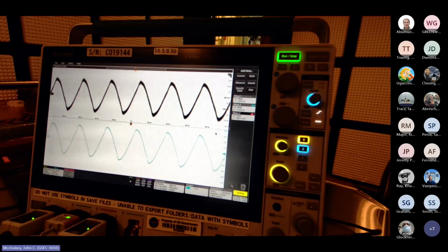The main thing is if you're doing the pre-calibration step per tradition, as defined decades ago, it was really only about voltage, because it just wasn't really standard practice to monitor the current directly in real time. But now we have that capability, and that's one of the points I'll be making here. So I'm just going to record the signal generator setting for what it takes to get the 1 volt RMS, and then I'm also going to record the current.